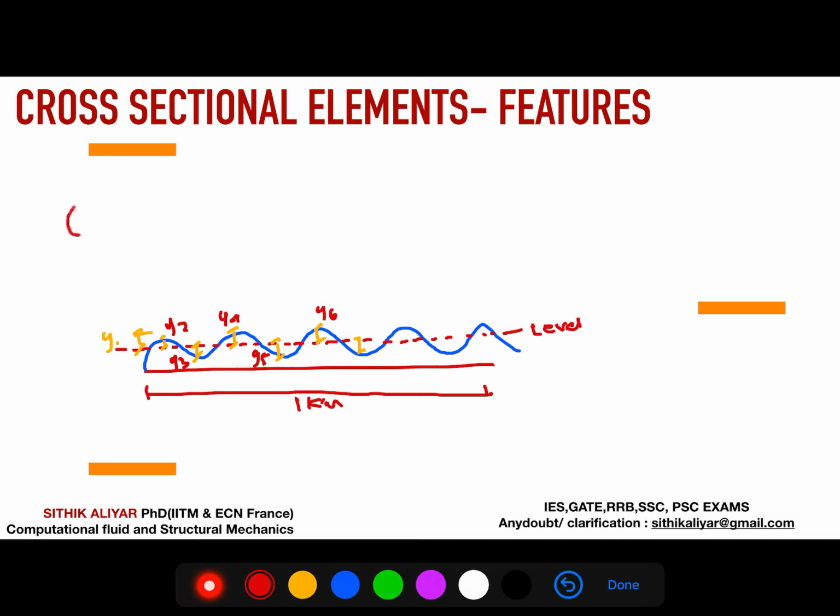You can measure the unevenness by the UI, the unevenness index, which you can measure using something called a bump indicator. You can google that if you want. Using that instrument, you can measure these bumps, which are the values I have shown here, y1, y2, y3. These you can measure from the bump indicator.